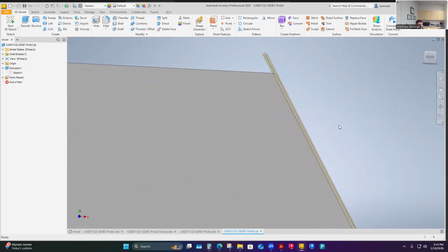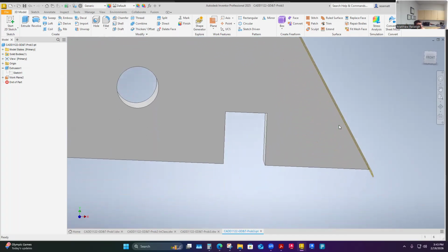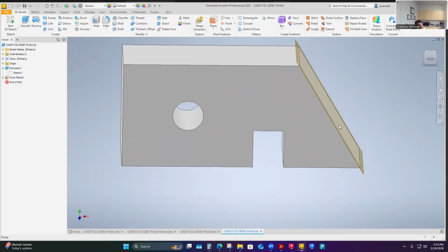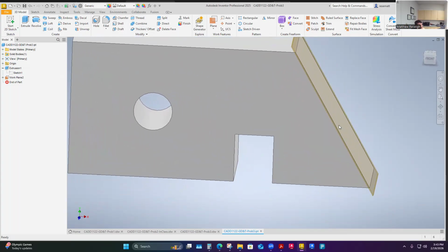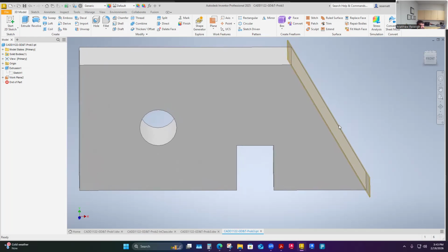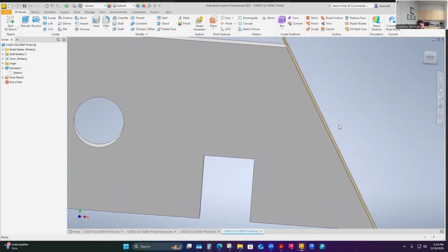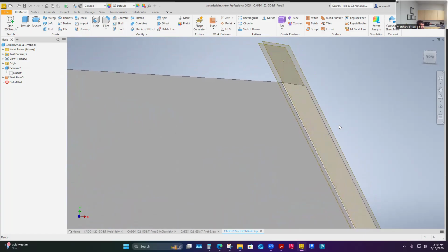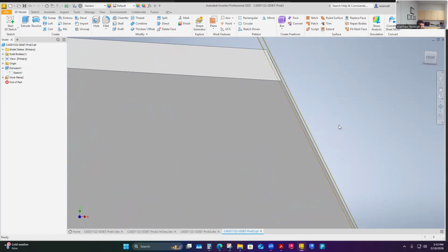And this is what that geometric symbol is telling me as a manufacturer: once here's datum A being controlled, or set down in our simulator to control it, I can measure this angle and however that's been manufactured, I need it to fall between those two planes to be an acceptable part.